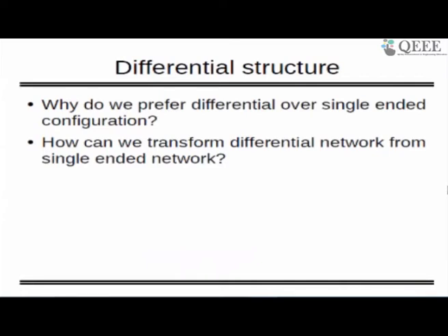Look, we categorize this structure in 4 different parts, but why do we prefer differential over single-ended at all? One technique may be to remove the VCC noise which was coming, but still it's not justifiable. Look, for doing that only, we could have used one big capacitor to kill that noise which is coming from the input side or from the rectifier side.